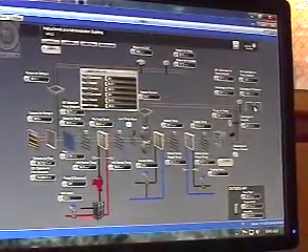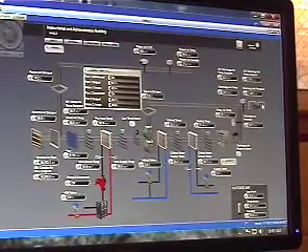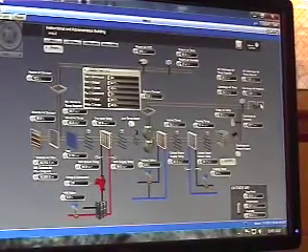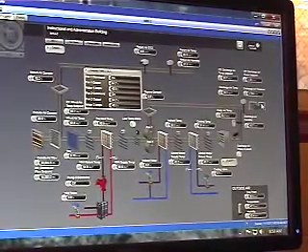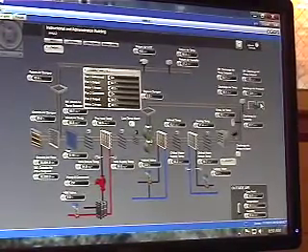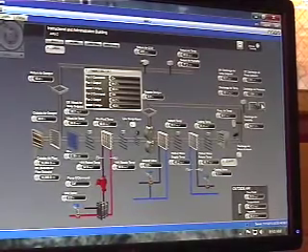This is your discharge air pressure right here. If I remember right, this does reset off of VAV damper position. So as your dampers open and close, that set point will go up and down. I believe the minimum is like 1.75, somewhere around there. But they will modulate up and down. We're trying to maintain your damper positions to have no dampers greater than 90% open, but trying to save energy as much as we can.